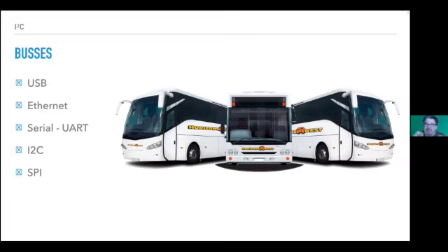So that means that if you have a memory chip and a CPU chip on your motherboard, then you have to have 64 wires going across. So wasn't there something we could do that's a little bit smarter? Maybe not for everything, but for example, if we just need to figure out what is the temperature on this motherboard, then we need a temperature chip, but we don't need to read it that fast. I mean, the temperature doesn't change that fast.